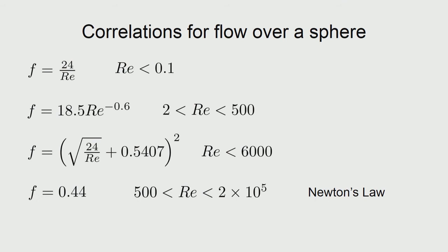And we can then see how the friction factor was modeled in experimental correlations for the rest of the Reynolds number regimes. So, this is laminar, or strictly speaking the creeping flow regime, and these are basically in the turbulent regime. You could see that the friction factor expression is given in different manners in the different regimes.